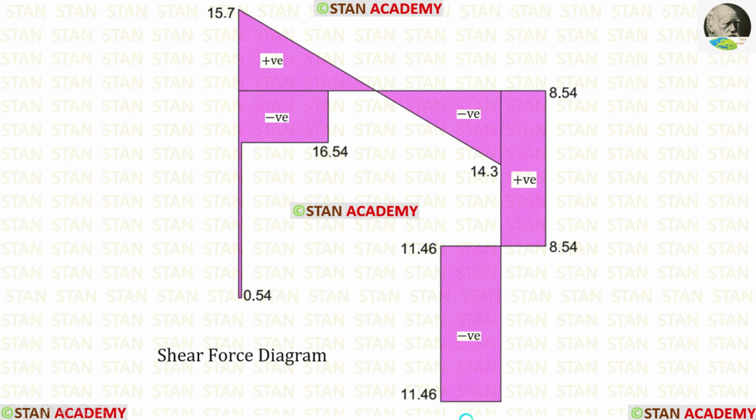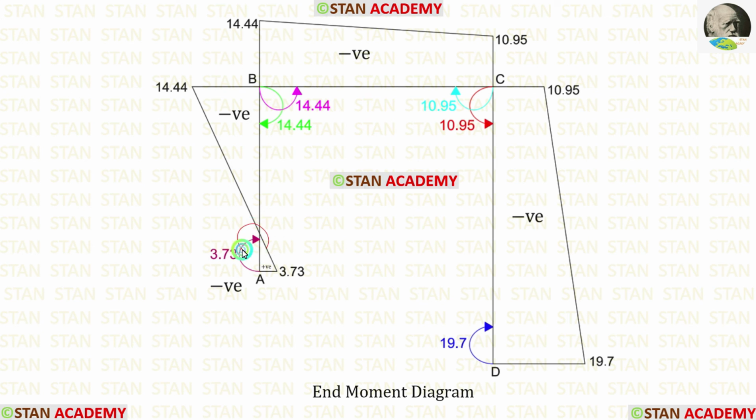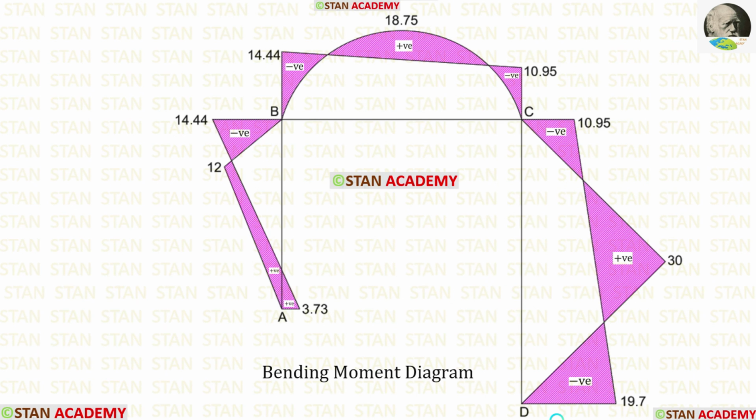Using the reactions and loads, we can draw the shear force diagram. Using the formulas, we can make the free moment diagram. Using the direction of the moments, we can make the end moment diagram. Then we can combine both of the diagrams and get the bending moment diagram.